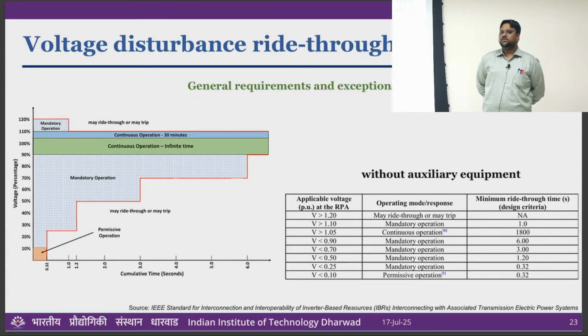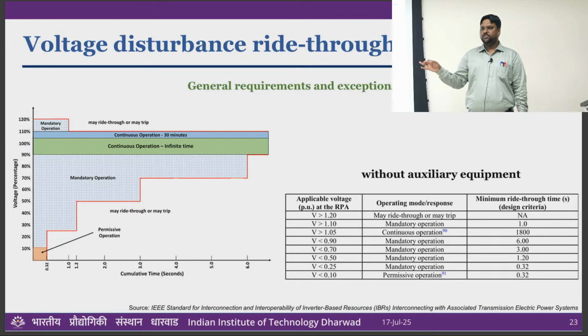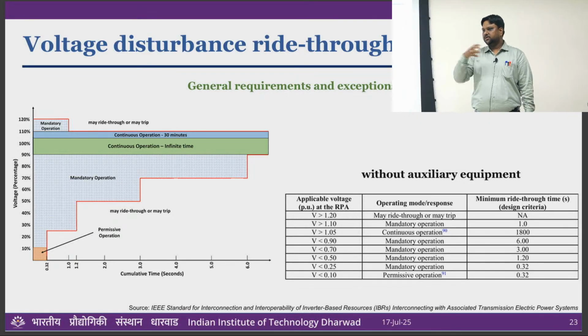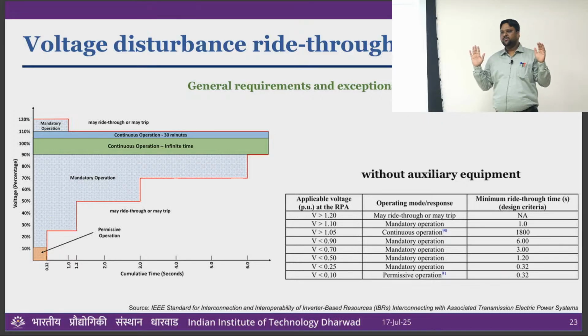Yes, that is one thing. But my question is, sometimes, what is the real time issue? Because when a fault happens, you don't listen to the PPC. The IBR will not listen to PPC instruction. The IBR will activate its fault ride through control. So the PQ reference it will take from the fault ride through controller. So what happens? The IBR, at 89% voltage sag, the plant requires you to inject reactive power, but at the inverter you see voltage is 91%.